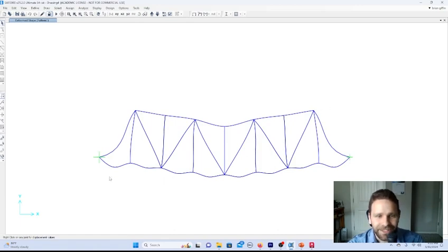Now we can visualize some interesting results. For pattern 1, the loads that we applied to this structure, you'll notice the deflected shape looks quite exaggerated. We notice that there's definitely some deflection downwards at the point of application where we've applied a load, and there's quite a lot of deflection happening in the bottom members to which we've applied this distributed load. You can examine specific deflection values by hovering your cursor over specific points in the structure to see how far it's deflected. In this case, not so far. SAP will amplify displacements in order to make them more visible. Just bear that in mind, that these aren't actually representative of the true displacements that the structure would experience.